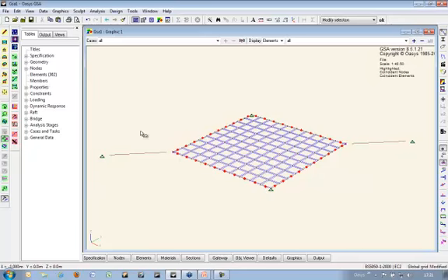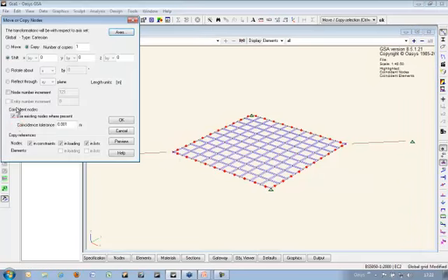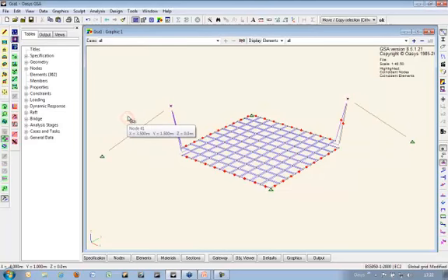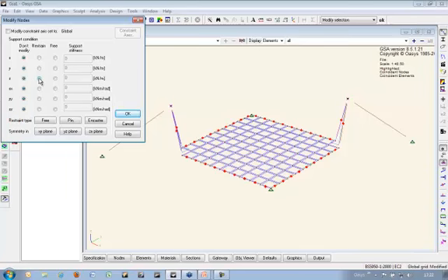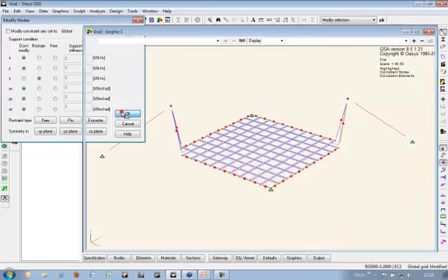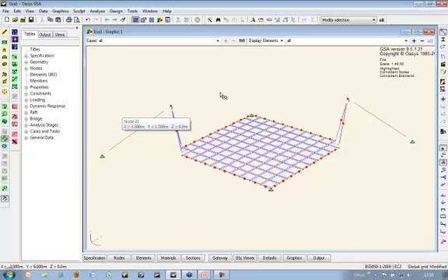These 2 points here, I'm going to move these two up by 2 meters, and I'm also going to modify those so that they are restrained in the Z direction. So to begin with, during the form finding anyway, they can only move horizontally, they can't move vertically.